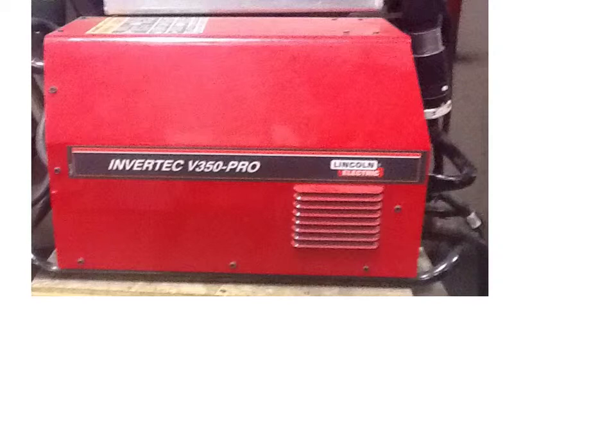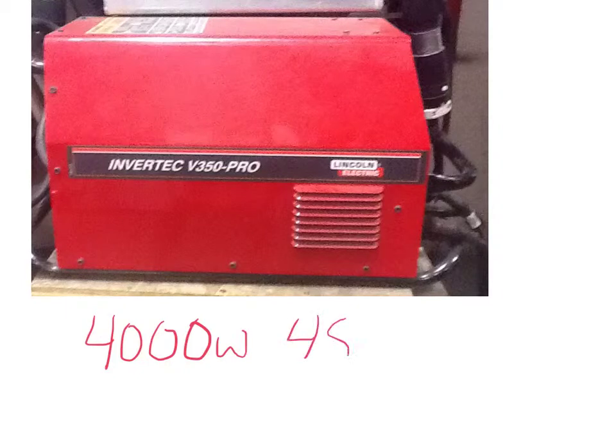Here's a second example. This is a welding unit, and this welding unit has a rating of 4,000 watts. And we're going to use 480 volts as a source of potential for this welder. So I am interested in knowing what the current value is going to be. Solve for current for this welder with 4,000 watts and 480 volts.